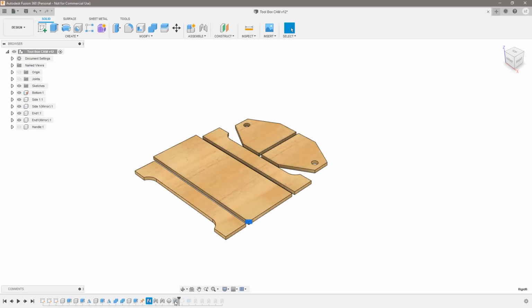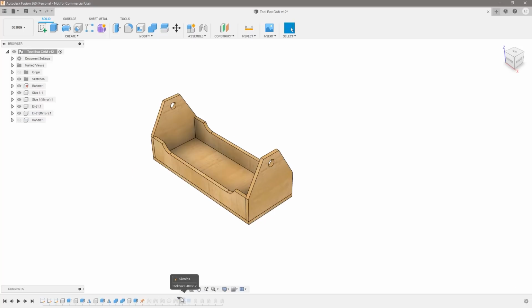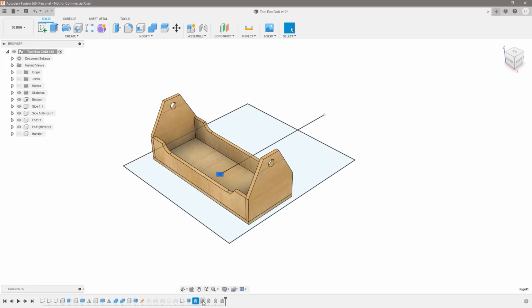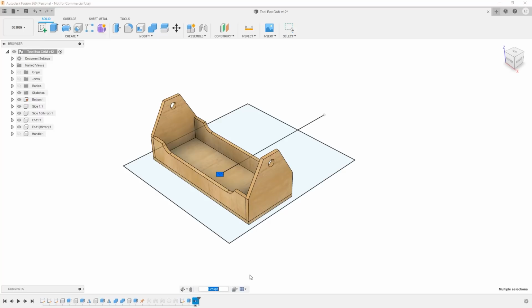And if I just select those here and I just suppress them for a second, there were also some joints used here later on for the assembly. So this one kind of has 2 different types of configurations. And you could group these together. So if we select these and we right click, we can create a group, and that group we can rename so it gets a name. So this could be, as assembled.